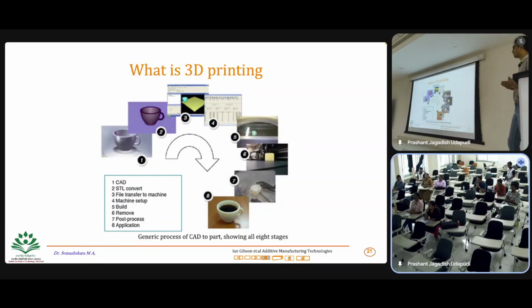With any other representation, you will not be able to represent the finest component or part, especially a complex structure like a sphere. If you use triangles, you can capture the entire sphere; if not with larger triangles, then by decreasing the size of the triangles you will be able to capture or represent the entire model.